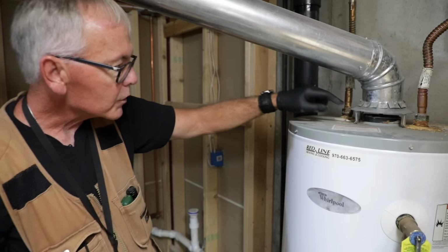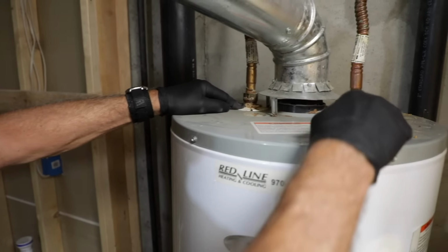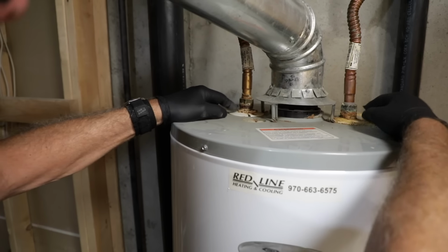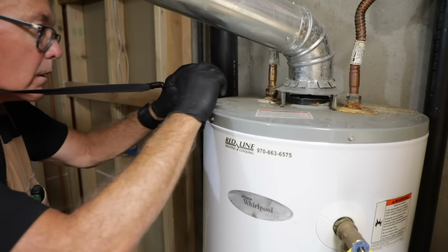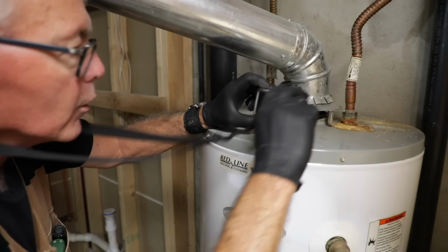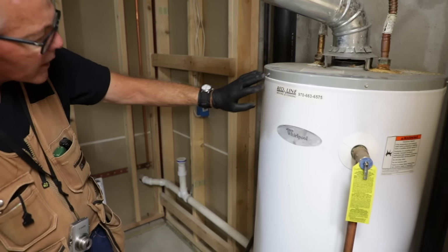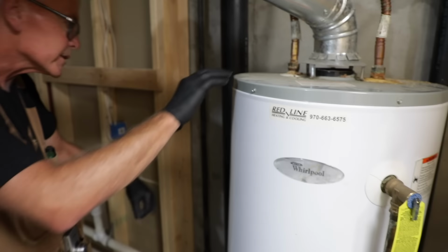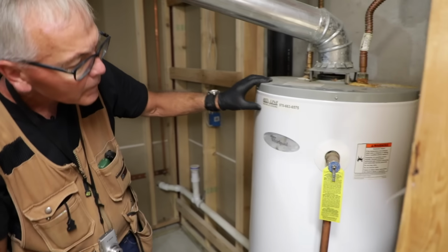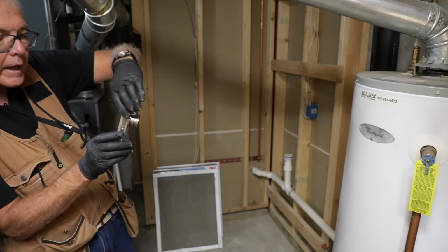And now I'm going to move on to the top of the tank. I can see right away I've got some corrosion on both sides, right below the dielectric fittings. So I'm going to take some photographs, put that in my report, and I'm going to recommend that a plumber take a look at that. So moving on down, next thing I want to look for is some seismic bracing. And it appears we don't have any on this water heater. So I'm going to go ahead and take a photograph, and I'm going to recommend that in my report.